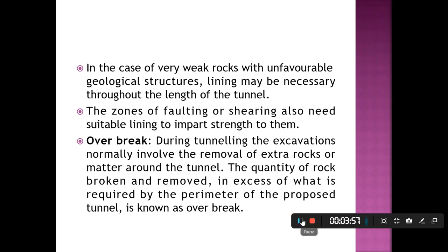In the case of very weak rocks with unfavorable geological structures, lining may be necessary throughout the length of the tunnel. The zones of faulting or shearing also need suitable lining to impart strength to them.